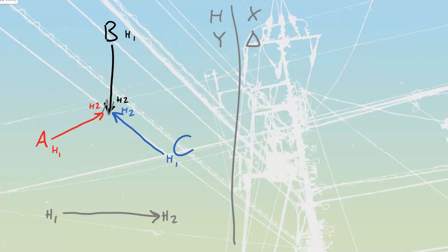Now that we've got that labeled, the next thing to do is work on our secondary side. Now we know on our secondary side that what we're ultimately looking for is a triangle inside of here. But we need to build the triangle out of whatever our primary side was built out of. In this case, it's built out of these three arrowheads at these three angles. So I'm going to draw right now my secondary sides as smaller ones, but I'm going to maintain the arrowhead. It's critical, this maintaining of the arrowhead in the same direction as what I have on my high side.